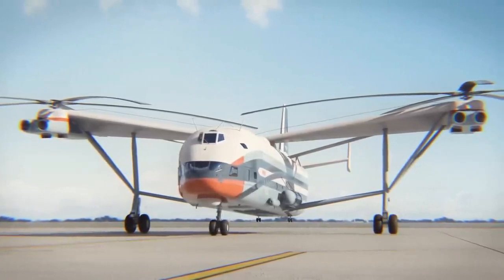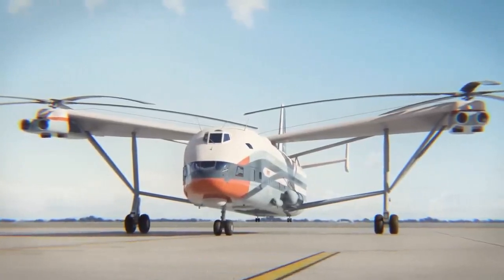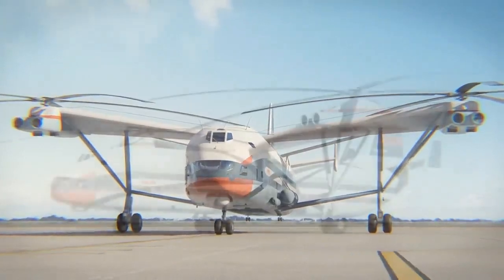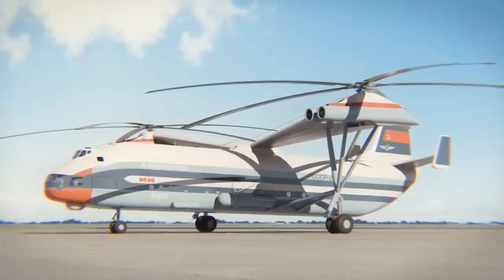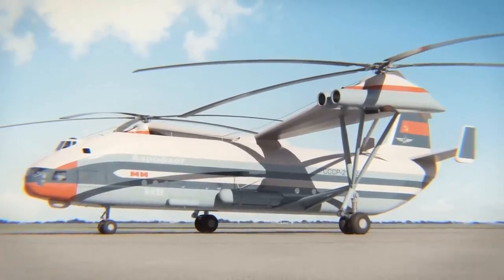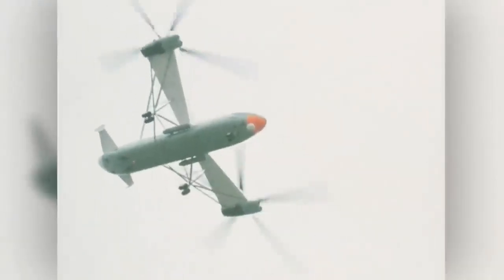Transverse rotors are mounted on the end of wings or outriggers perpendicular to the body of the aircraft. Similar to tandem rotors and intermeshing rotors, the transverse rotor also uses differential collective pitch. But like the intermeshing rotors, the transverse rotors use the concept for changes in the roll attitude of the rotorcraft.